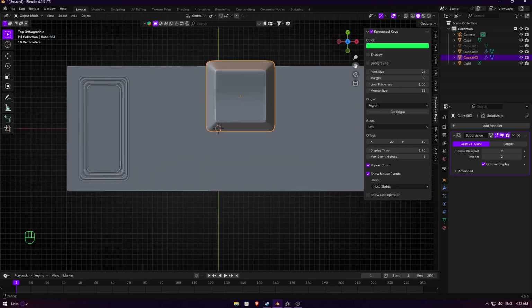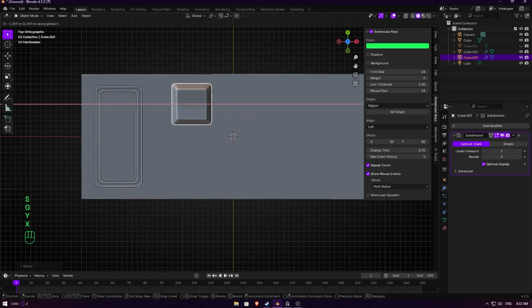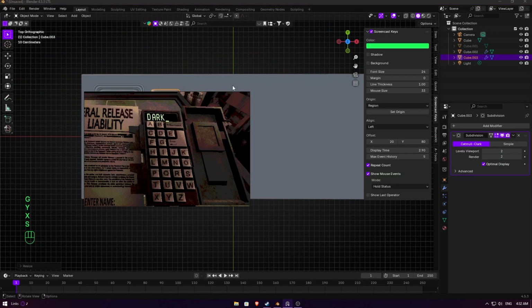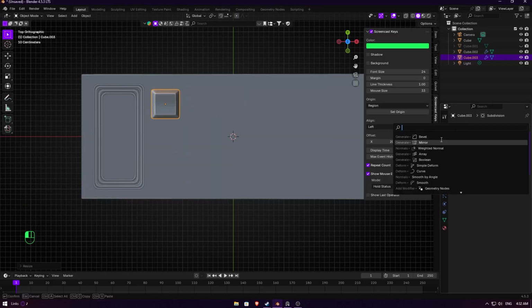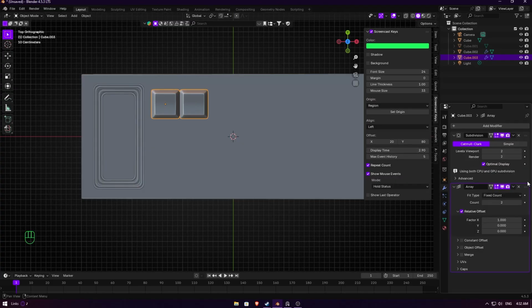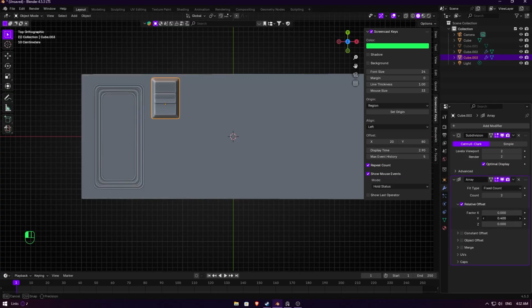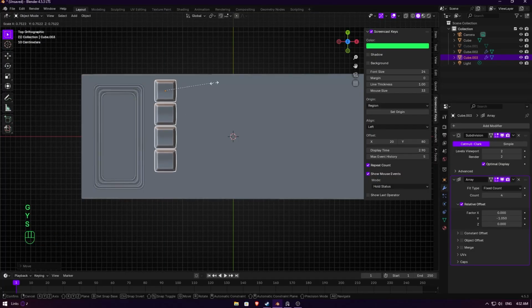So with this key, I'm gonna go here and scale it down, and try to assign 4 keys in a row. So like this, and we're gonna go modifiers, array, and X make it 0, and Y-axis maybe -1. Or -1 and more, and 4 is gonna be good.